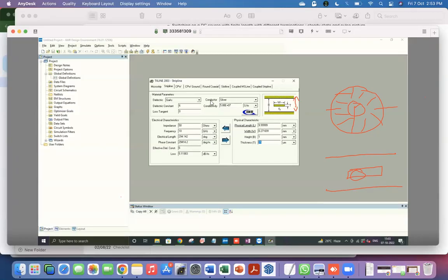And so let's move on to the microstrip very quickly, just to remind you of the structure. So no top ground plane. And the main difference is that if I now look at this effective dielectric constant, it's 4.45 for something which is specified to be 6. Right? It's lower because now part of the field line is in air as well. Okay, and then finally we looked at